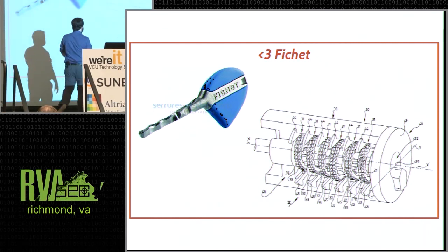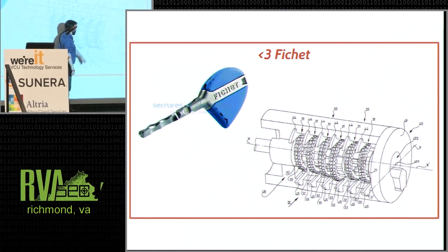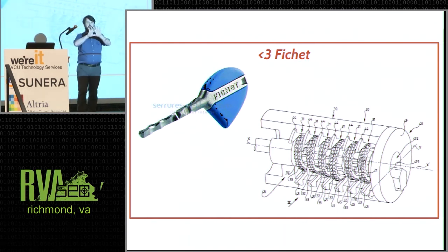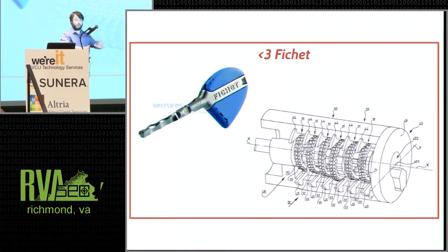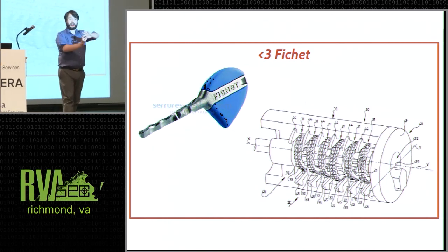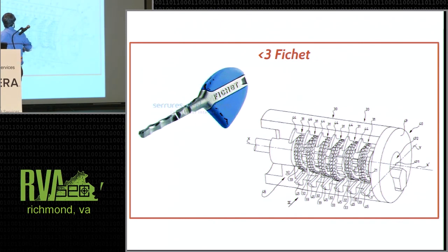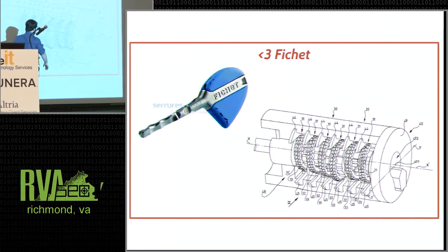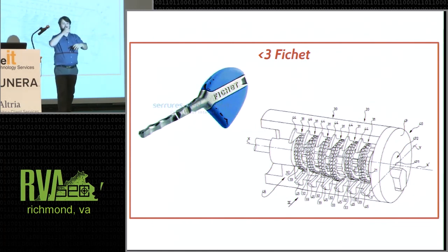Each of these gears, and there are 2 here, 2 here, 2 here, 2 here, and so on, have a triangular piece inside of them. The crazy-looking key moves through the triangle, rotating it into different positions. As it rotates, the gears act on these sidebar wafers. The sidebar wafers have little serrations that fit into the gear, and they're dragged along in a channel, and they have a gate.